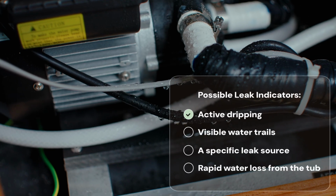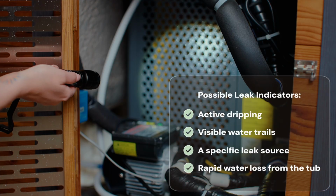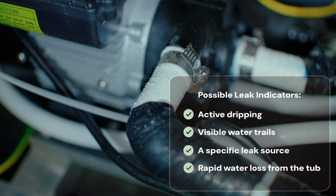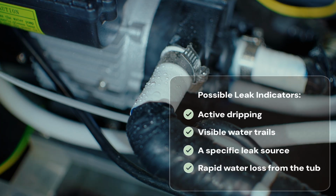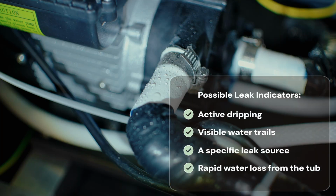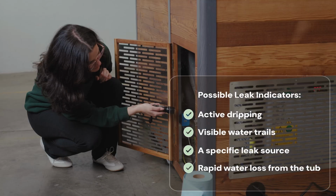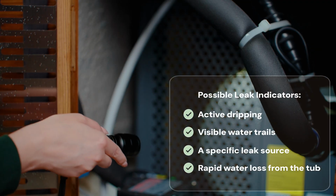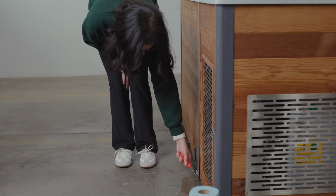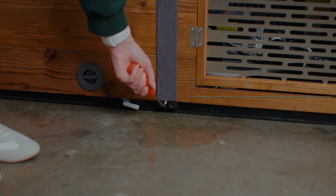Inspect all accessible plumbing connections, fittings, pumps, and equipment for signs of active dripping, visible water trails, or moisture originating from a specific component. If you can identify a specific source of the moisture, continue with the diagnostic steps in this guide. If water is present beneath the tub but no active leak source can be identified, condensation may be the cause. To access the plumbing and underside of the tub, the exterior panels will need to be removed.